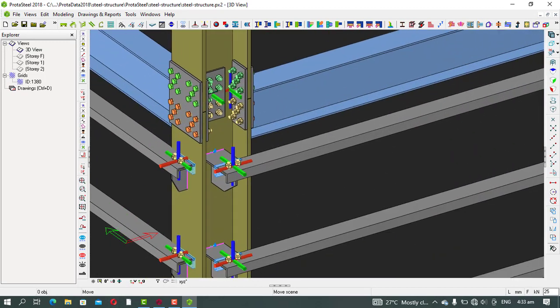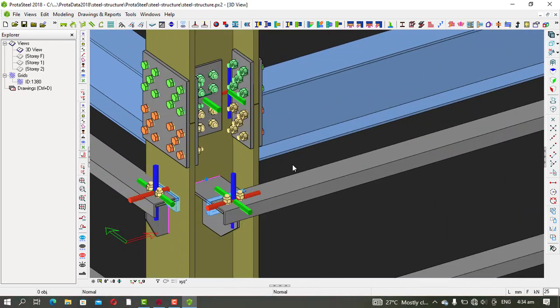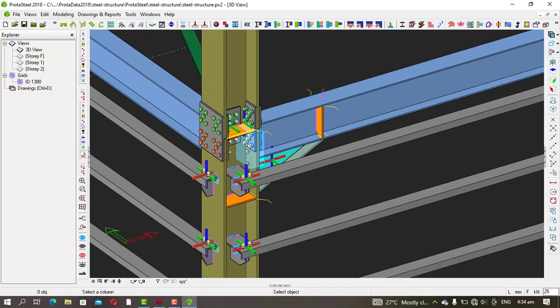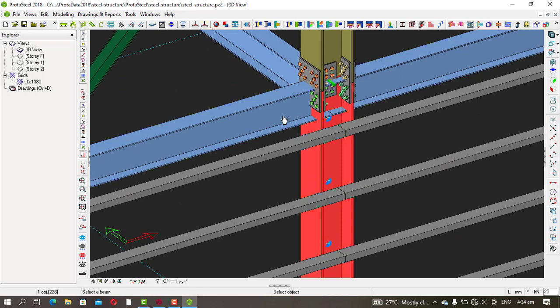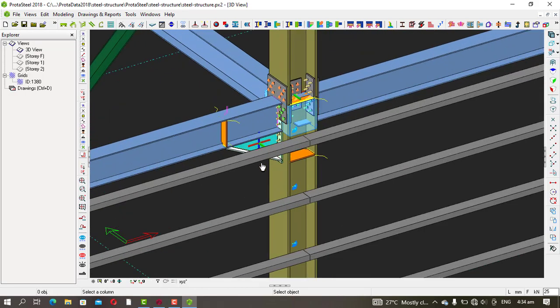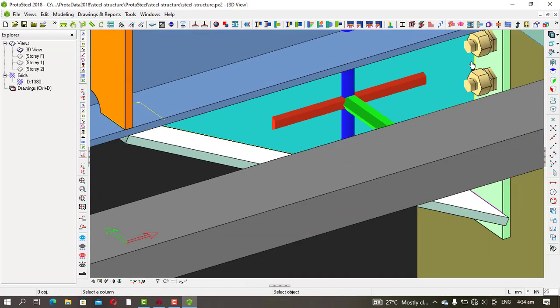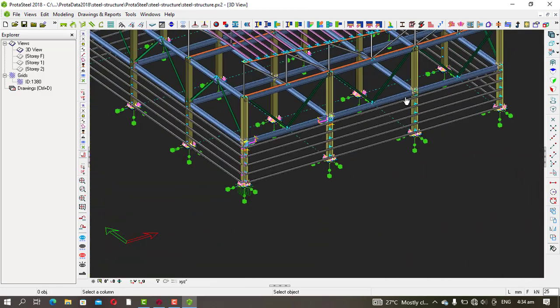Another thing you can do to connect the beam to the column is use a haunch. I like using haunch. So you can pick the haunch, then you click the column and then the beam, then you see the haunch. Okay, you don't need to right click. So you can do the same thing, this, then it will just drop in like that. You can see the haunch, and then you can see both connections for the haunch.